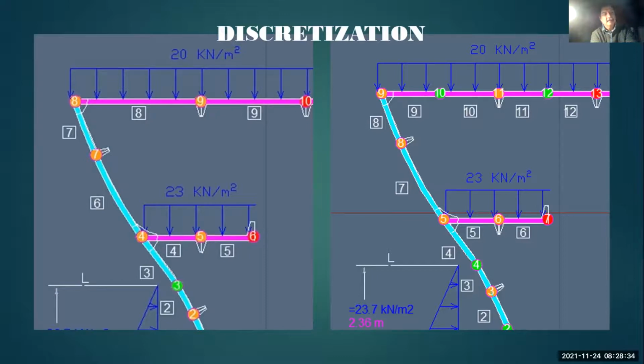Diaz right now, please. So if I want to set the displacement in the x direction of joint 5 equal to 0, then you will have to replace one element in the K matrix with a large number. What element would that be?